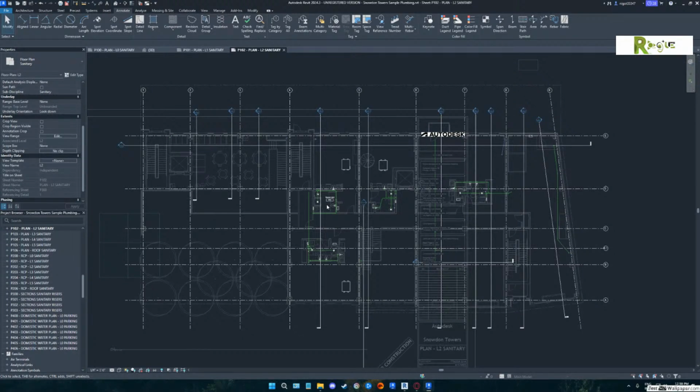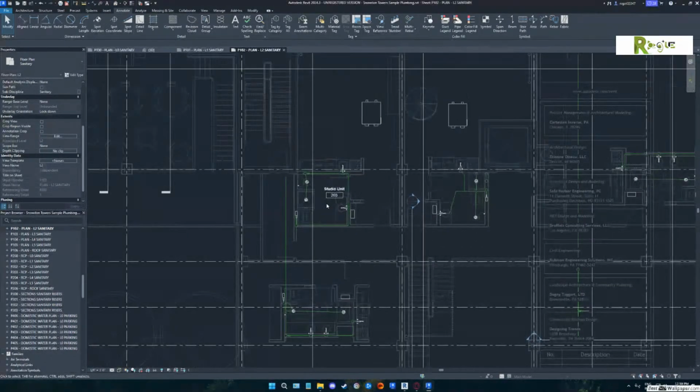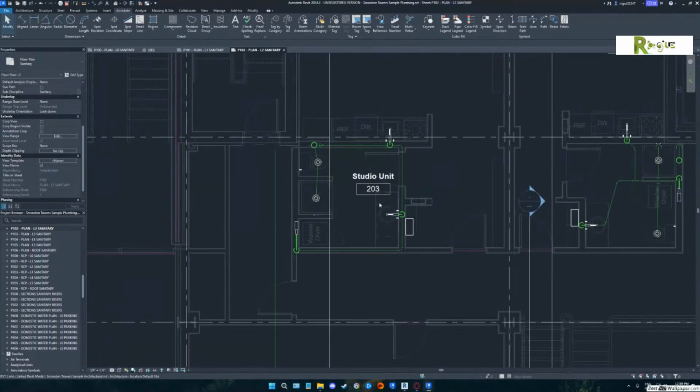So the first time through, you'll want to tag them. And there is some advantage on a drawing this size. You got to understand where that tag sits in this room can be convenient for the plumbing drawings, but that may not make any sense for the electrical drawings because that tag might be right on where the light is in that room.